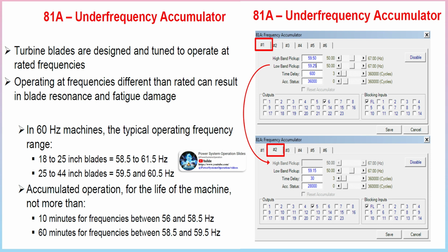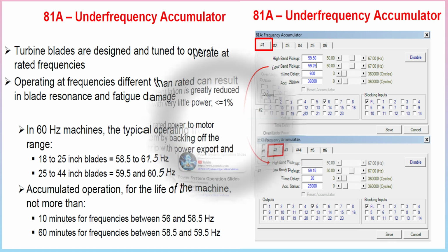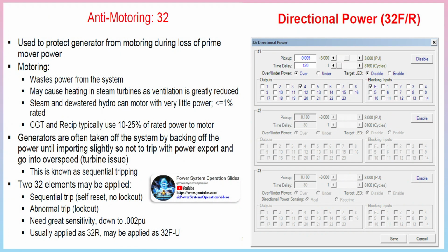This protection is not considered essential since the lubrication oil is normally obtained from the same pump as governor oil, and a failure of the governor oil will automatically make the stop valve close. Protection against loss of boiler firing. Two methods are available for detecting the loss of boiler firing. In the first method, normally open NO contacts are provided with the fan motors, which may trip the generator if more than two motors fail.